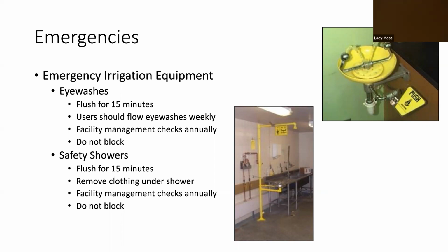We check the eye washes weekly so they don't get all gunky. And then the facility checks them annually. Make sure you're not blocking them so that they're easily accessible to whoever needs them, because keep in mind they're going to have something in their eye. So they're not going to be able to see to navigate around obstacles.